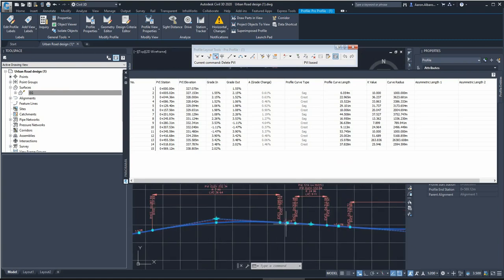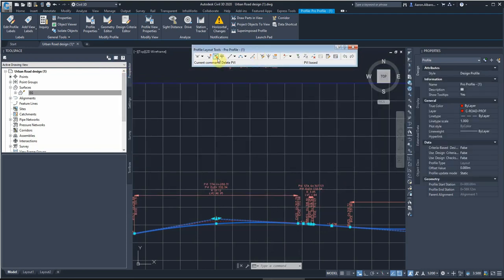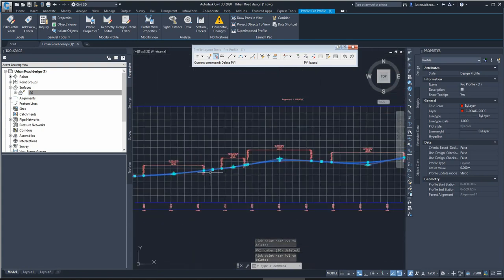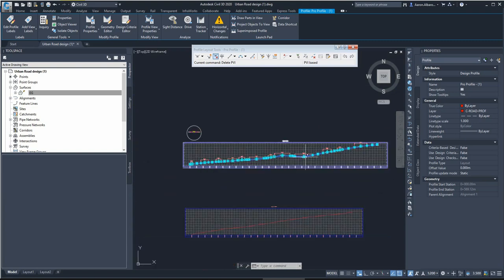If that's the case, what I'll need to do is just remove this in a minute. I will make it smaller, as small as possible, so I can remove it in a minute and increase this K value up to 10. Now I'll just close here. I'm looking at the K values, all of them higher than 10 other than this one. Go back and just click next to that, enter, and that's it. So what we got so far, if you notice, we've got best fit profile. All the K values, they meet our requirements.